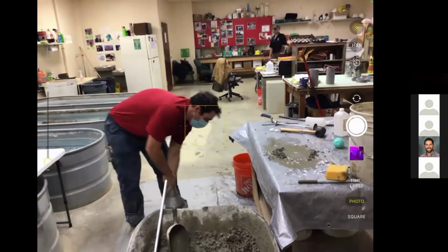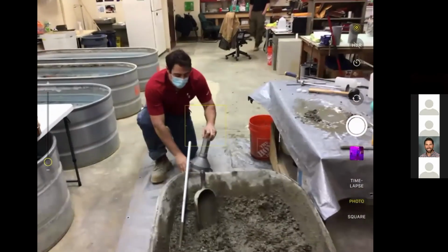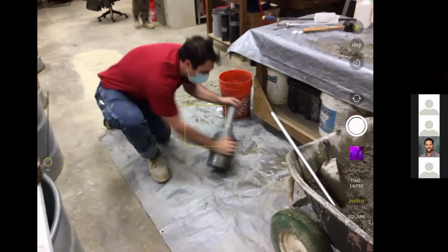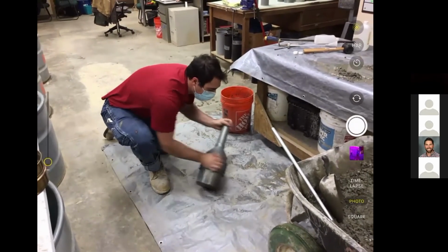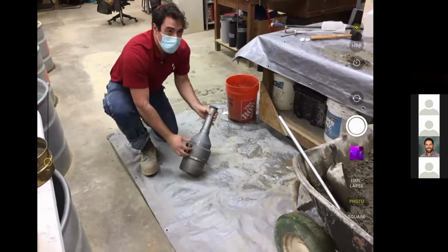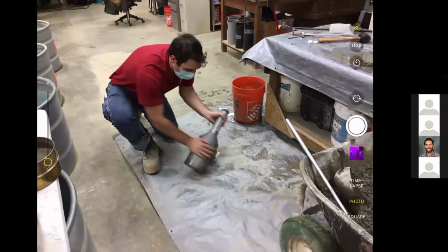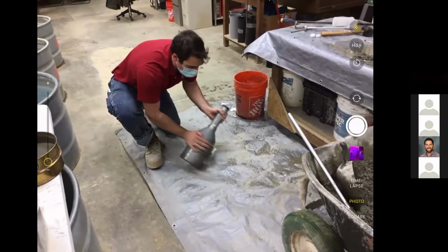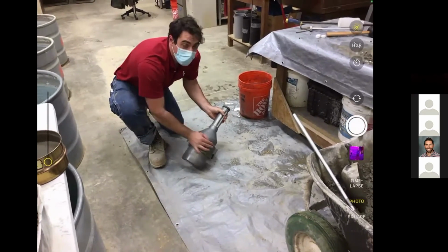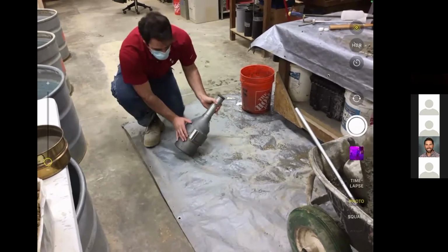We'll then take our rollometer, we'll bring it to the floor. We're going to tip it at a 45-degree angle. We're going to shake it in quarter to 1/2 turns in a shearing motion to make sure that we loosen up all that aggregate inside our pot. We're going to rotate the pot 1/3 turns to make sure that we're breaking up all that aggregate. And we'll do this for a total of 1 minute.